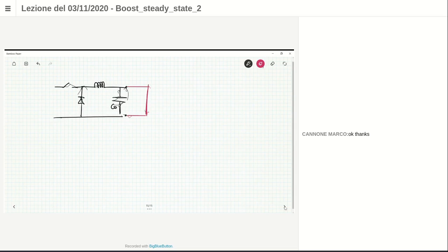You have a short here, and you recognize the presence of this short. Then you can open the switch, and immediately you can interrupt the current flowing from the input side to the load. So the buck converter can easily manage the short circuit at the output, because the transistor is in series with the power flow.